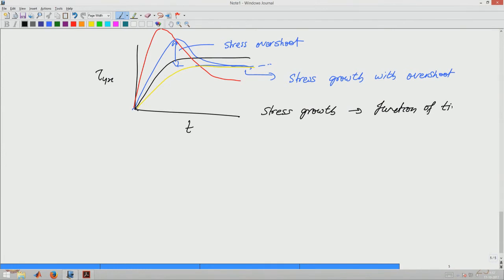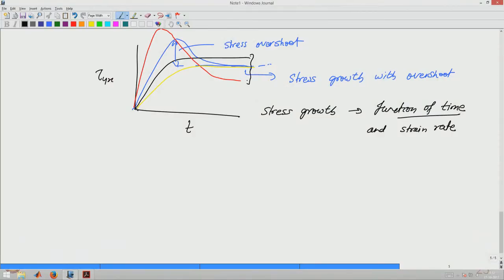It is a function of time, which was the earlier case also, and also strain rate. So, many of the nonlinear responses of materials are according to what we have discussed so far, that at very low strain rates where deformations are small, we would observe stress growth to be monotonic, but as the strain rate is increasing, when higher strain rate is applied, a stress overshoot is observed, and usually the stress overshoot is higher and higher when strain rate is higher. Of course, the steady value of stress may depend on the overall magnitude of strain rate being applied, and in fact in the drawing here what we should look at is the fact that each of the stress values that you will get will be higher than the previous one, as the stress will be higher, but the viscosity may be lower.